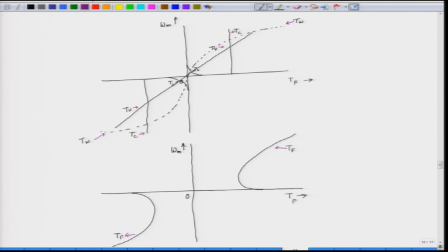What we now see here is that when the motor is at rest, we have static friction and Coulomb friction present, while viscous friction is 0 and windage friction is 0. When the speed picks up, the viscous friction and the windage friction increase, the Coulomb friction is constant, and the static friction vanishes. So, this is the plot of frictional torque.